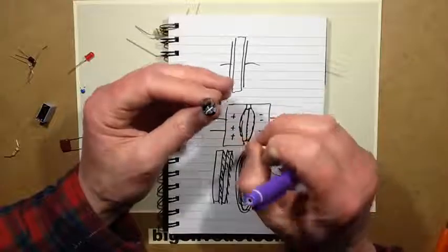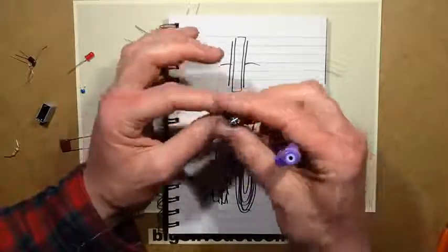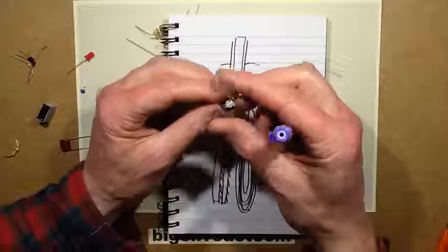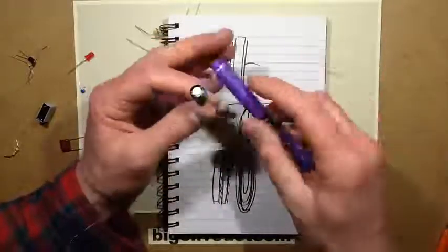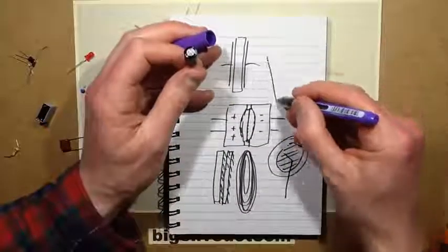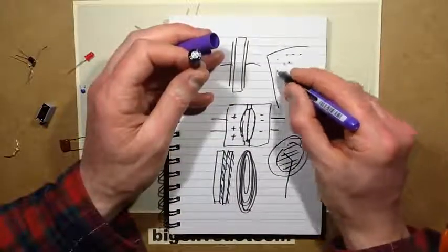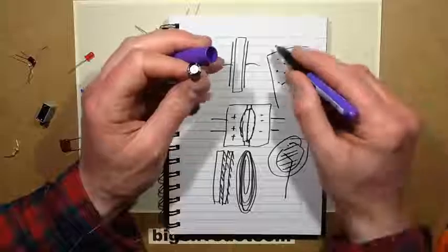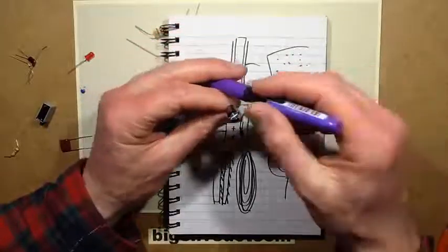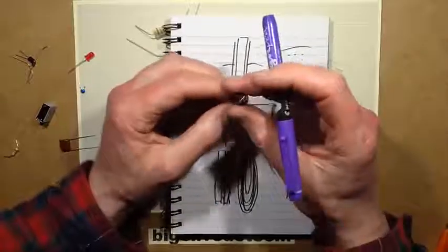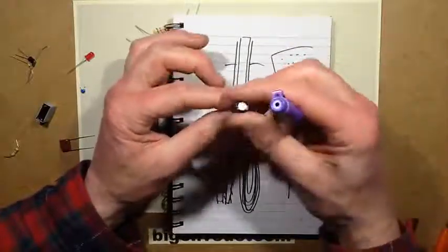And that means it really is like micron thick, which means that they can get a very high capacitance in a small area. But to couple onto that surface, they have to use a liquid electrolyte, because if you looked at the foil, it would look all pitted and mottled with that oxide coating. So to get a good coupling, they use a liquid that just fills in those gaps. And that's one of the downsides of, well, it's many of the downsides of the electrolytic capacitor.